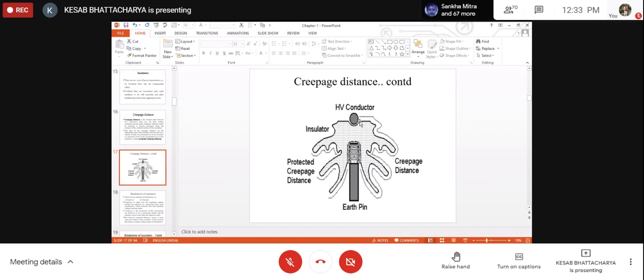To this groove at the top, the high voltage conductor is normally passed. But just remember, high voltage conductors are not just placed on the top groove; with the help of binding wires, they are tightly and securely placed. There are side grooves which are used for tightly fastening the conductors on the top groove.